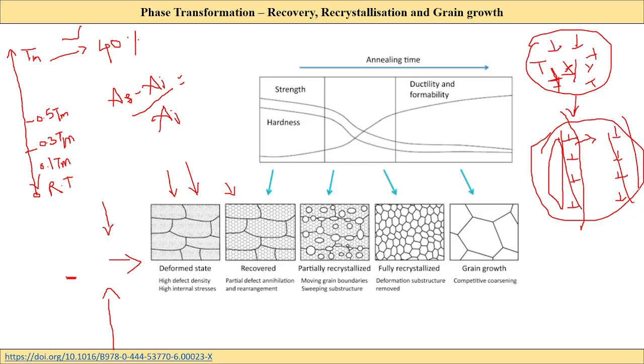They will form at grain boundaries, again because the grain boundaries provide accommodation for dislocations. That is the perfect place to accommodate those dislocations. Once the dislocations get accommodated at certain points, that part will become a boundary, and the part beside it will become a strain free region, and that's why we say a new area is born there. That is the new grain, or we call it a strain free grain.